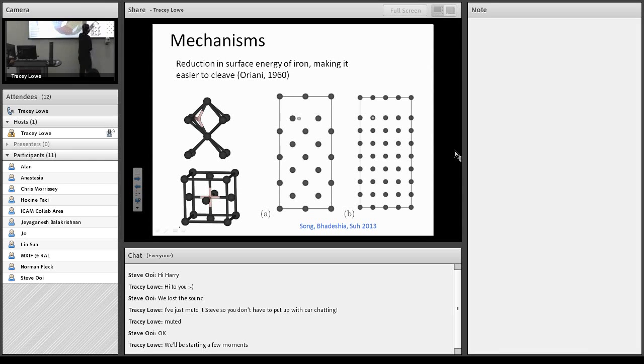Hydrogen in ferrite, unlike carbon, occupies tetrahedral interstices. It sits most comfortably in tetrahedral rather than octahedral interstices. This is tetrahedral; octahedral would be in the middle of that object. Whereas in austenite it sits preferentially in the octahedral interstices.